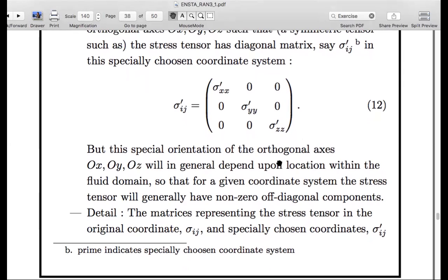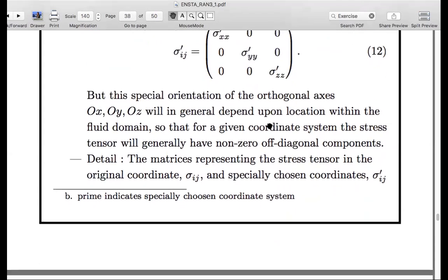conceptually it's interesting to know that these complicated internal stresses, well, there's always a reference frame in which they have a simple interpretation. They all collapse onto these normal stresses. If we chose our coordinate system correctly, they'd be normal stresses. So they would be compressing or pulling apart a little cube oriented the correct way, right? A way we're not free to choose. We have to choose it so that the stress tensor becomes diagonal.